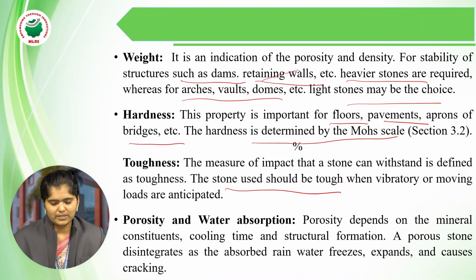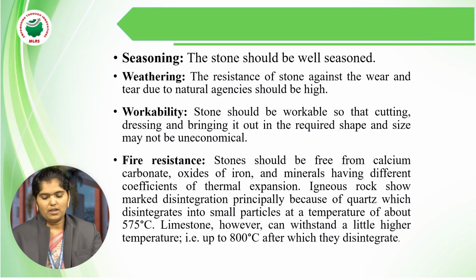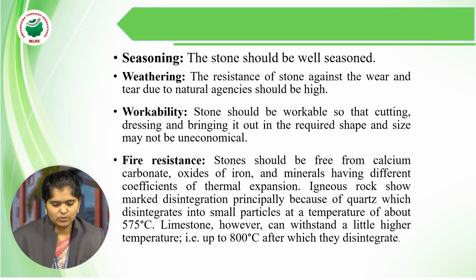And next, porosity and water absorption. Porosity depends upon the mineral constitution, cooling time and structural formation. A porous stone disintegrates as absorbed rainwater freezes and expands, causing cracking. Next, seasoning. The stone should be well seasoned. Weathering: the resistance of the stone against wear and tear due to natural agents should be high.